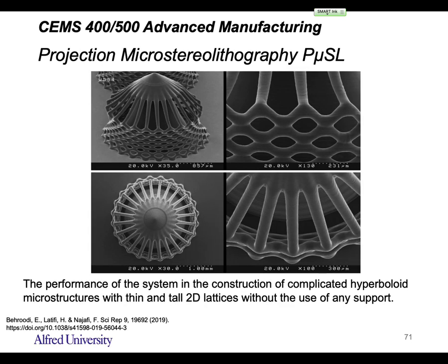So that's the setup. Of course, there are a lot of simulations of the optical path, and if you design your machine quite well, you can achieve pretty good printing results, right? So this is from the literature published last year. They engineered that macro stereolithography system, and this scale bar is 300 micrometers, right? It's not that small, but this line width will probably be around 40, 50 micrometers, right? If you can imagine, that resolution will be way better than 50 micrometers, right?